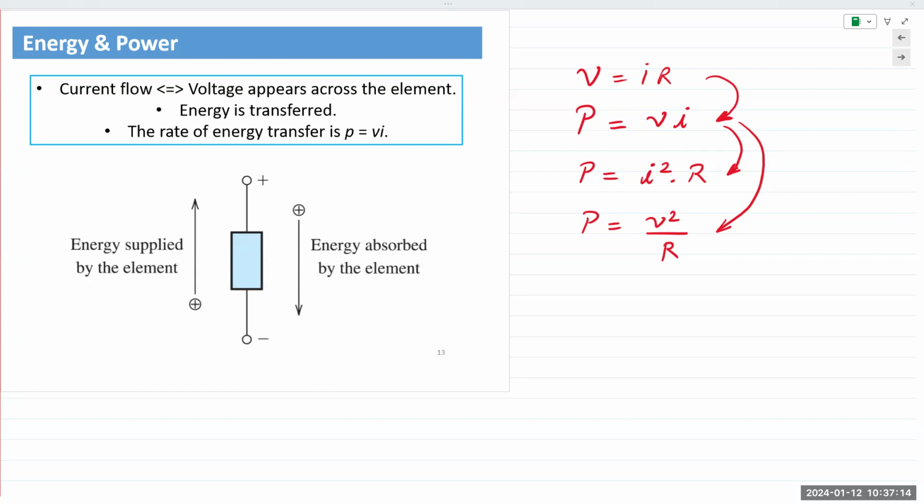No, right? Power and energy have a physical basis in real life. It's not negative. We assign positive and negative so that we can balance out the equations and solve that circuit. So anytime a source is supplying power, supplying energy, we put a minus sign in front of that number. Think of it as money.